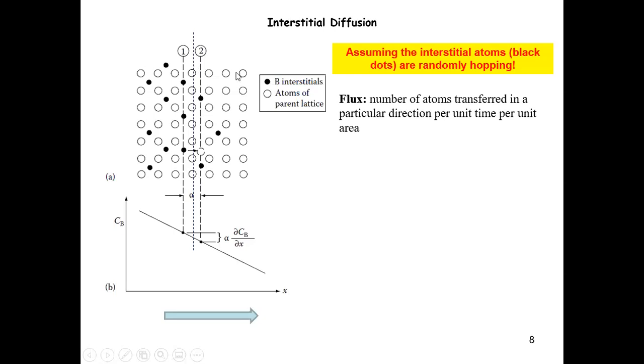This is a similar picture that you have seen before, but it's static, of course. We consider a crystal structure formed by these large white particles, which you can consider to be ions, and then small black particles, which you can consider to be carbon, taking the interstitial positions. Again, this is a schematic plot, so I'm just showing a two-dimensional plot in a very simple square lattice, just for demonstration. You can work out the more detailed mathematics for any three-dimensional lattice with a more realistic packing structure of the atoms.